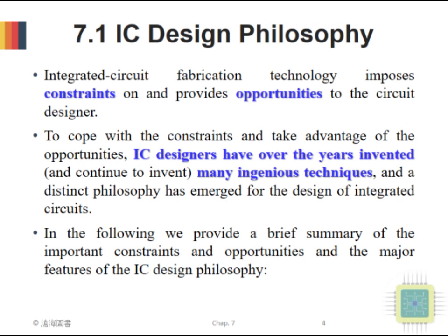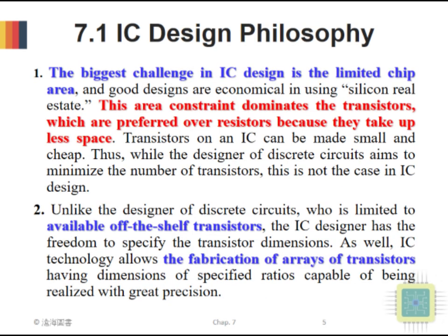IC designers have over the years invented and continue to invent many ingenious techniques, and a distinct philosophy has emerged for the design of integrated circuits. In the following, we provide a brief summary of the important constraints and opportunities, and the major features of the IC design philosophy. First, the biggest challenge in IC design is the limited chip area, and good designs are economical in using silicon real estate.